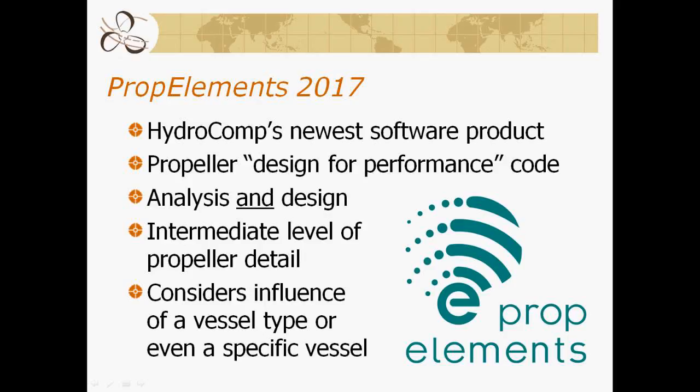We'll see a little later on where it sits in the propeller design and analysis process, between tools like NavCad, for example, which uses parametric methods to describe and calculate propeller performance, and a full three-dimensional CFD. PropElements also is what's called a wake-adapted code, so it considers the influence of a vessel type or even a specific vessel. And that's an important concept to carry through here: PropElements can be used to represent semi-custom, vessel-specific or vessel-type applications.